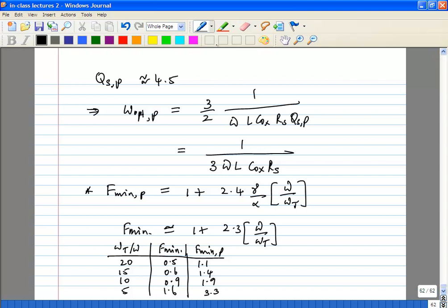As long as you choose a properly normalized omega t or omega. So where does your power come in? Power comes in through your omega t. If you burn more power, you can actually get better omega t's, if you have control over the width and the current consumption. So you choose omega t based on that.